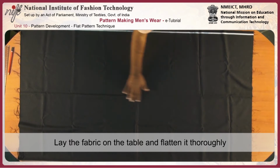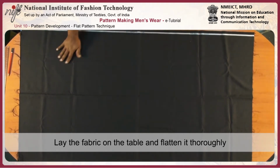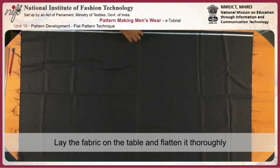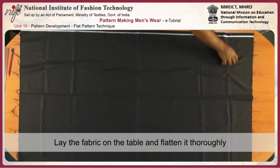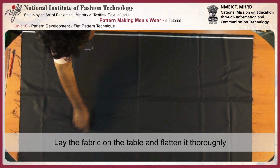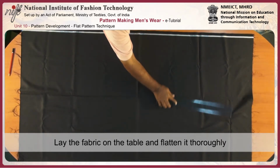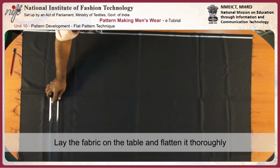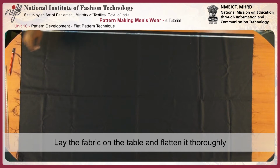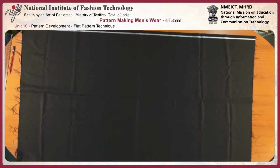Ensure the fabric is spread flat without any overlapping, and the edges, that's the selvage, are facing towards the marker, that is the cutter. Then flatten the fabric. Since it is on fold, we need every pattern piece single.